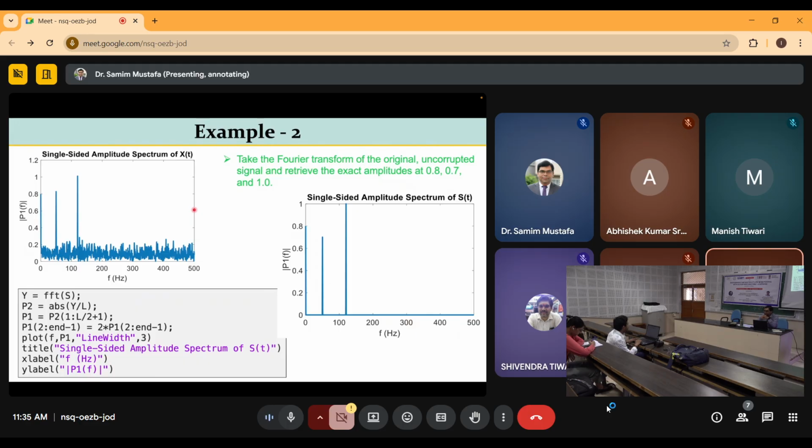So that is the thing: every system, even us, if you model me using my entire stiffness and mass matrix, assembling all the parts, you will see I have a certain frequency. Some other person has a different frequency. Every object has a defined configuration and defined material property, so it has a defined natural frequency, which is fundamental to that object, at which it vibrates, right? So if you see the FFT of the measured response from that object or structure, there will definitely be some peak observed in the FFT or power spectral density, meaning whatever you are plotting in the frequency domain.